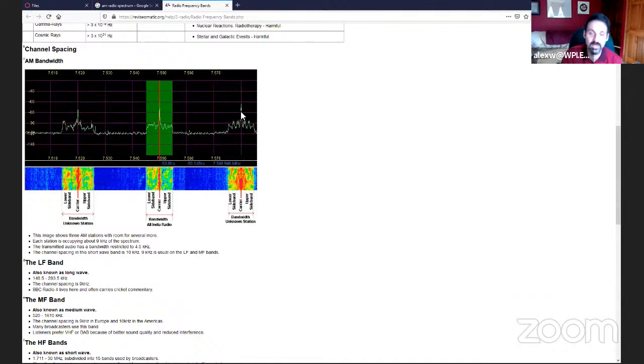So in many ways, that's a really nice feature to have in terms of establishing a lock. Of course, the bad side of things is your dynamic range now is also quite a bit, it's double. So that means that your radio equipment, especially amplifiers and other nonlinear components, need to make sure that you don't do something called clipping.